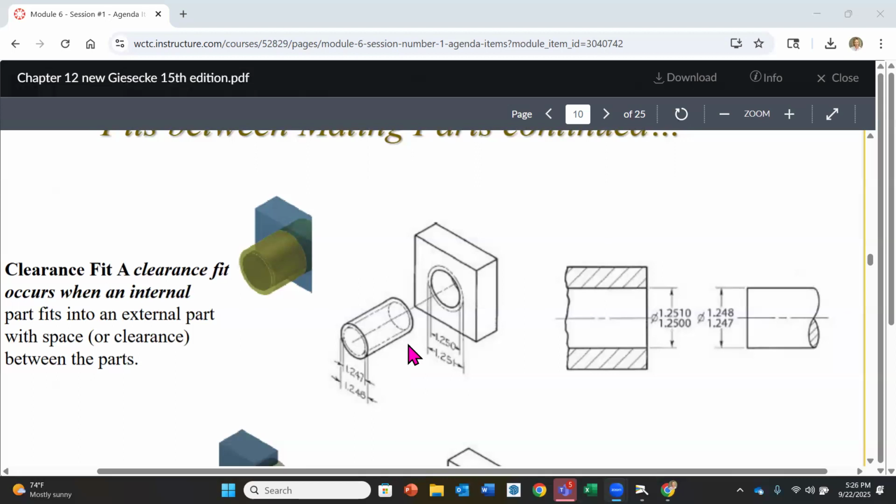So now if I need it to be a little bit smaller than the nominal size, a 1/4 inch, all I got to do is push that tool in a little bit, and now I just take a little bit more material off. But in the case of a hole, we want to go with a nominal size because we're kind of stuck with that. So that internal feature is where we usually want to have our nominal size on. All right. And then you can see the zones here.